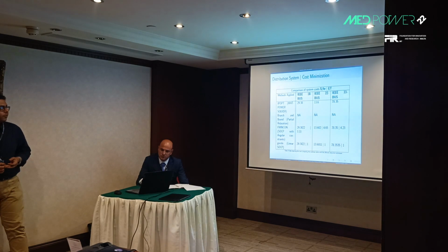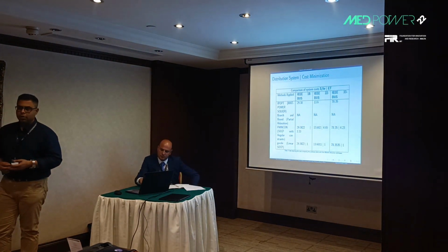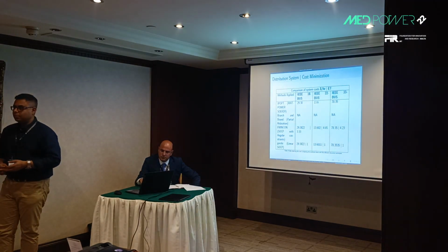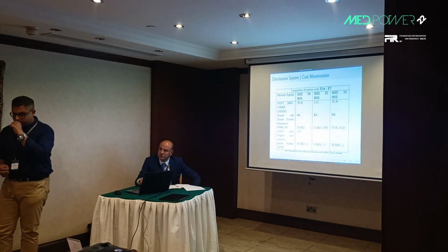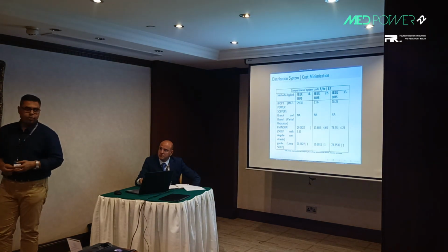But the only problem is that with the partial relaxation we are unable to find a solution for the distribution networks because of the sparsity of the Jacobian and the admittance bus matrix that is formed.